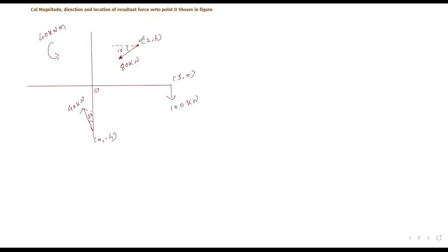So here the 80 kilonewton load, I have drawn random xy axes here. Your force is in third quadrant. So our resolution is just like this. Keep in mind, you have to do this resolution in the exam. You have to consider this; it is not given in the data. So such a resolution will come. Everybody with me, please confirm. And your angle with x-axis, that's the reason 80 cos 10 degree. This is 80 sin 10 degree. I hope it is clear to all of you.